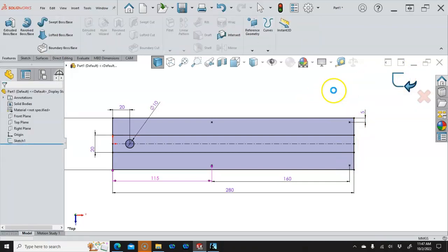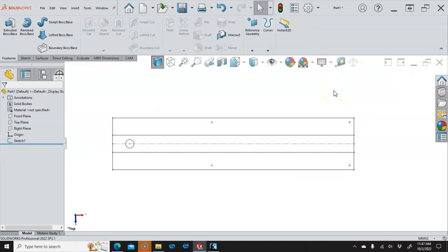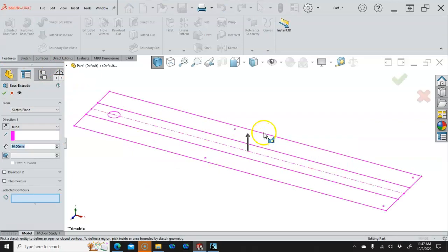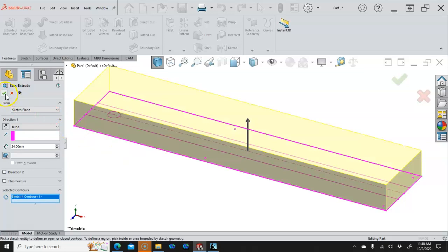All right, so if this was a true layout sketch, then I would leave this. I would probably rename it and leave this, but we can go ahead and start building up our geometry. There's not too much in the way of complexity here. So go into the sketch, tell it to extrude. If I want to go with contours first, and let's see, our overall height is 44. But the first stage is 24, so let's start with it. And we'll pick that geometry.